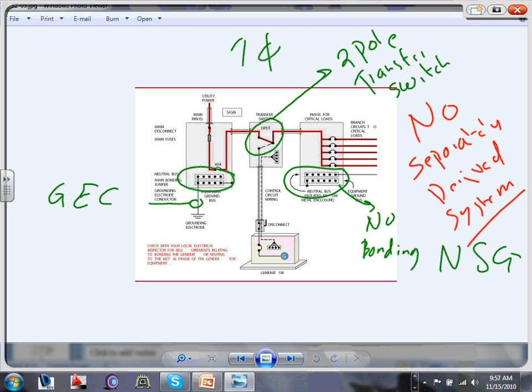The last thing I want to bring to your attention here is the control wire. Can you see these dotted lines? These are control wire right in here. You have to bring wires from the auto transfer switch to the generator, because when you lose power, you don't want to go there and manually transfer the switch. When the auto transfer switch senses that there's no voltage here, it sends a signal to the generator to start.